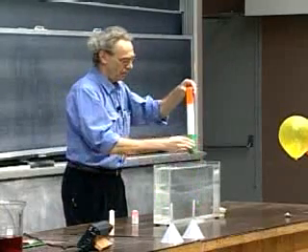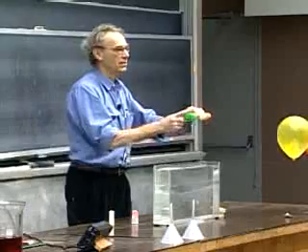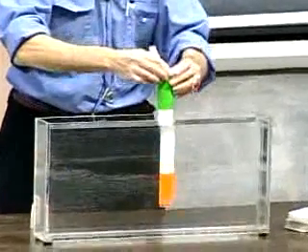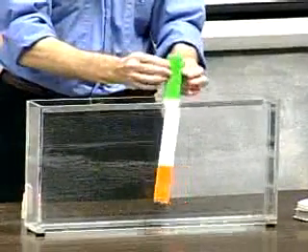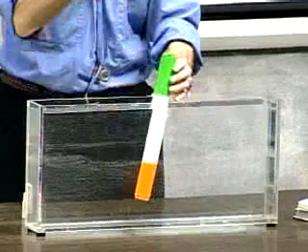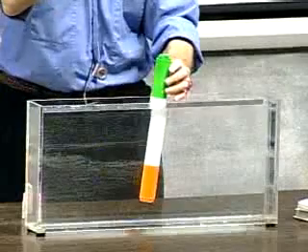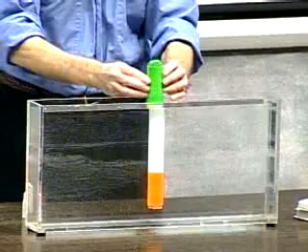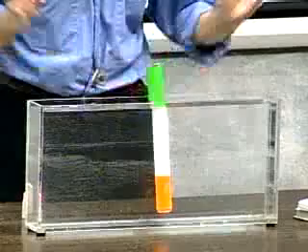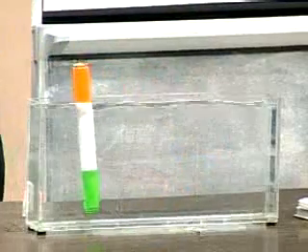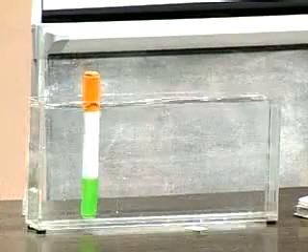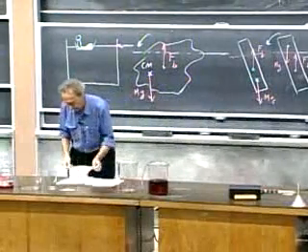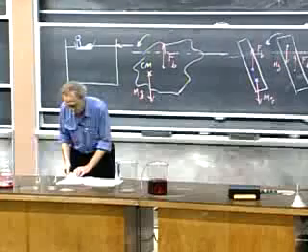So here, the center of mass is somewhere here. Very heavy, this part. And so now, if I lower it in the water, notice it goes into the water to the same depth, because the buoyant force is, of course, the same. So the amount of displaced water is the same in both cases. But now the center of mass is high, and this is very unstable. When I let it go, it flips over. The center of mass of the object was higher than the center of mass of the displaced fluid. And so with ships, you have to be very careful about that.